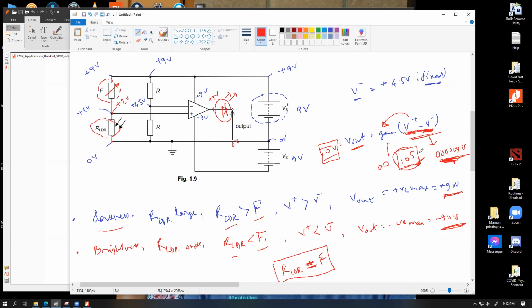This is for a real op amp value, but there are different values set, sir, for 10 to the power 3, 10 to the power 4 or 10 to the power 5. Yeah, you can design op amps to have different of these values from your factory. You can, but we don't usually do that because that requires very precise engineering. There is an alternative way to control this factor, which you are gonna see in a while.